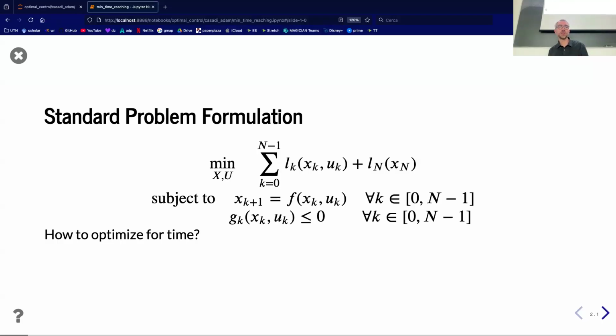Yeah, I mean, in some specific cases there are analytical or semi-analytical solutions to this problem. But if you want to tackle the general case, where you can have any inequality constraint for modeling joint position limits, joint velocity limits, joint torque limits, obstacles in the environment, then those methods don't apply. You just write the time t into your optimization problem, and then you optimize just over the time, because it's basically the only constraint you're giving.